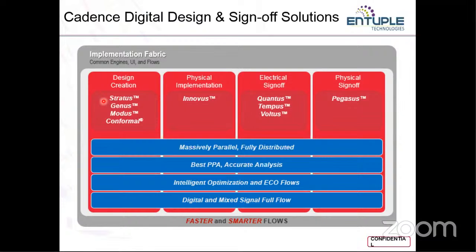It will help you in inducing faults to your design. You may have an idea about stuck at zero fault, stuck at one fault, built-in self-test: how to induce faults in the design and test their impact on the circuit. Modus gives you an idea about that, and Genus and Modus work hand in hand for DFT.